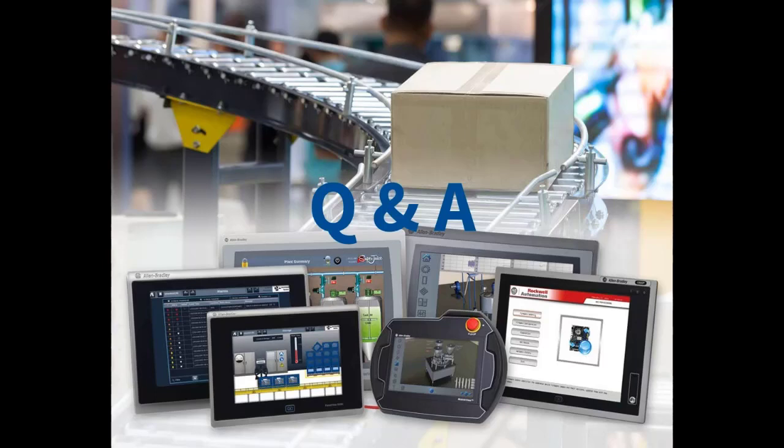Thanks, Dan. I'm going to direct one more to you. Is a UPS needed for the PCs to coordinate a shutdown? Yeah, that one caught me a little off guard, so I had to grab the manual real quick. But it is suggested that the computers be supplied by their own disconnect or supplied with a UPS, because we do want to ensure that the Windows operating system is shut down before we disconnect power to any of those products, including the PCs and the book mounts. So yes, that is the case.